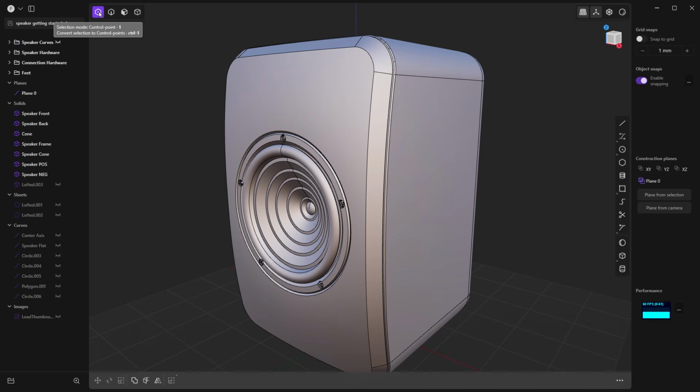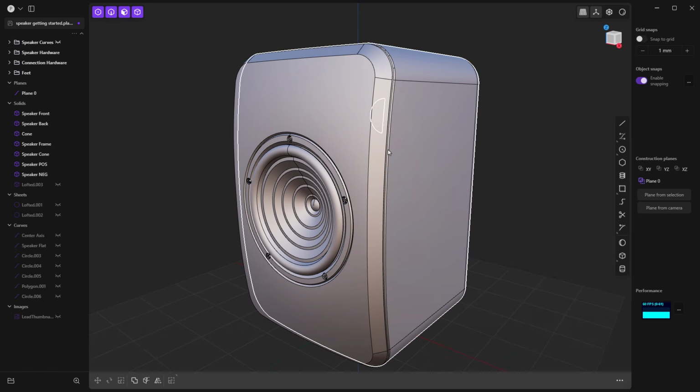There are times when we just want control point selections. For example, if we are working with complex curves that have a lot of internal control points, or if we're using some more advanced tools like raising the degree of a complex body, and we want to control it by pulling and pushing control points around, then you generally want to go to that control point option. Some cases you may not even see the control points if that's not active. So that's the option in the top left corner. Again, that's going to be our selection filter.